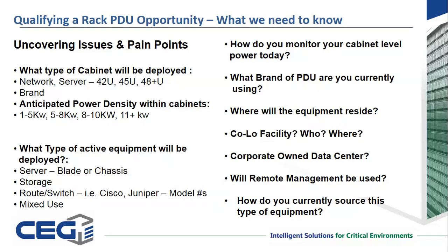Hey Rob, one point on the sizing issue. This is one definitely to be careful of as clients move into higher amperage on the PDUs and pin and sleeve connectors. Not all cabinets and floor cutouts have really been equipped to handle these larger pin and sleeve connectors. So you definitely need to pay attention to floor cutouts and cabinet cutouts in placing higher amperage PDUs.